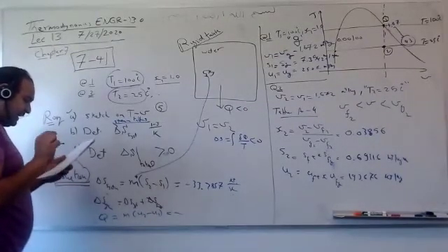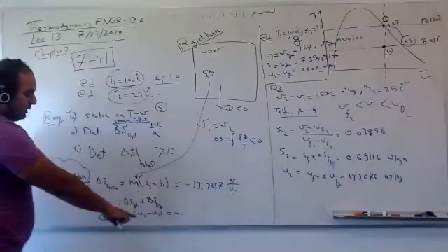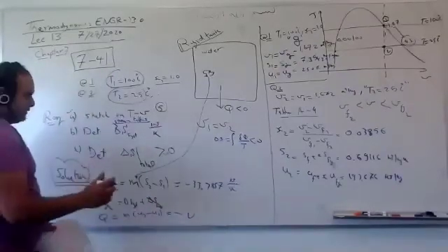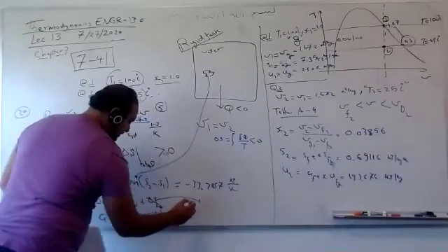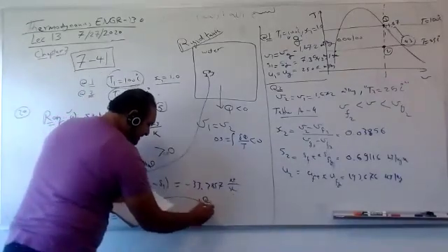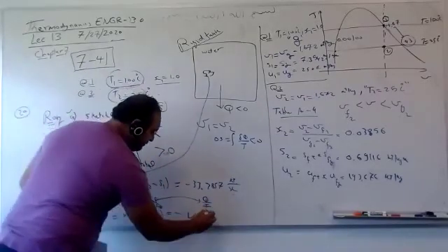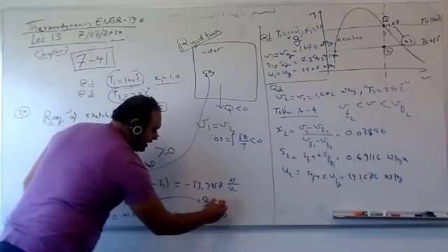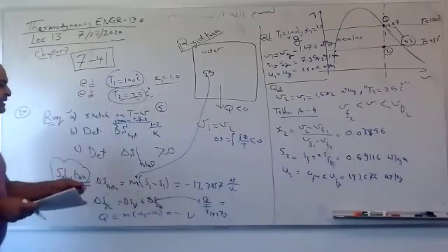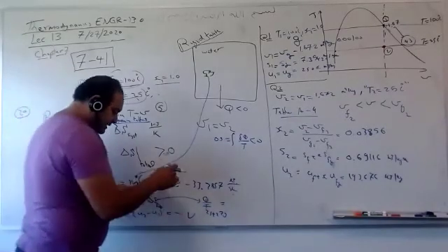Anyway, you get this Q. If you have U2, U1, and mass 5 kilogram, you can get this Q. So delta S surrounding is simply Q over T, and T was the same as 25. So 25 plus 273. Never, ever use Celsius in this ratio. In any equation, use Kelvin for temperature.